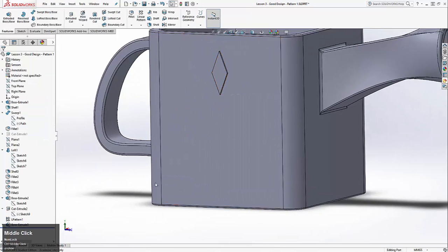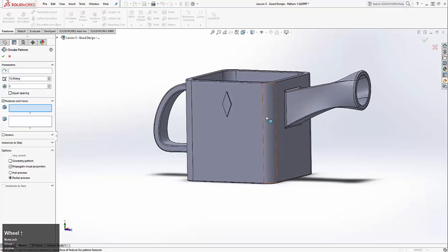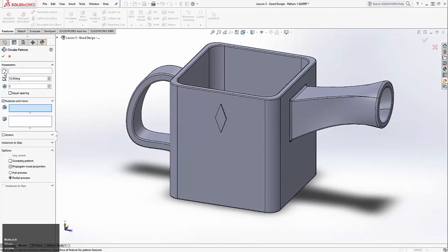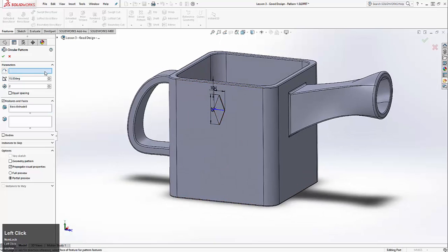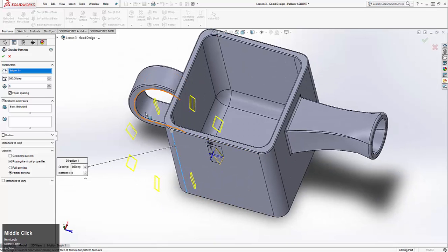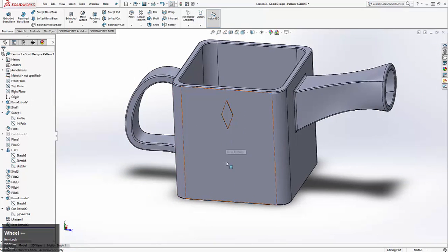We're going to do the star pattern. We did the circular pattern before in the assemblies, in the previous lesson with the assembly base. And what you need is an axis of rotation. So you can say that I want my feature right here, but if it doesn't know where to rotate about, it's not going to do anything. So you need an axis through the middle.